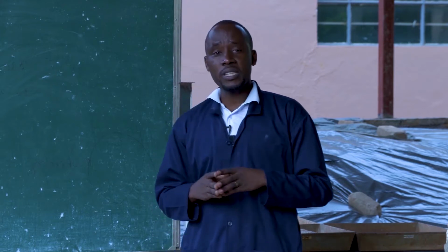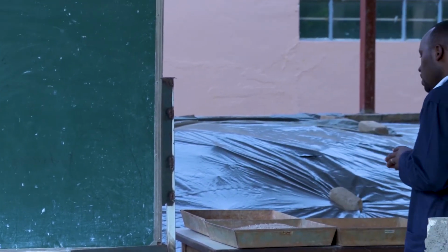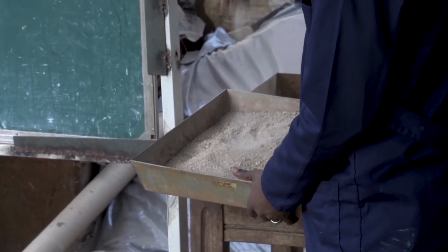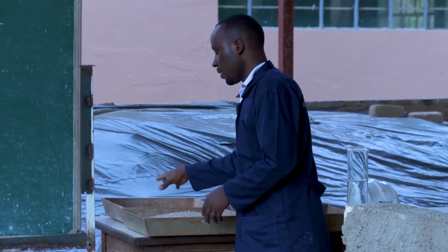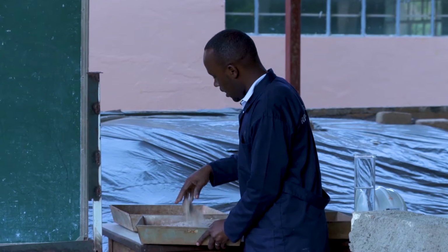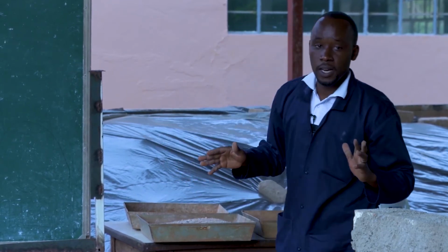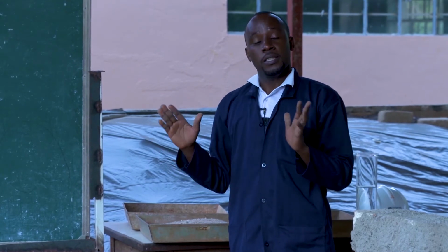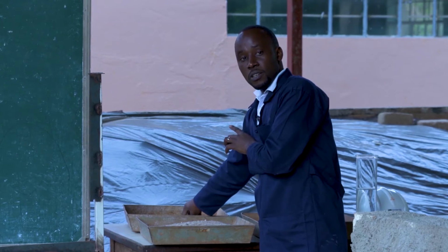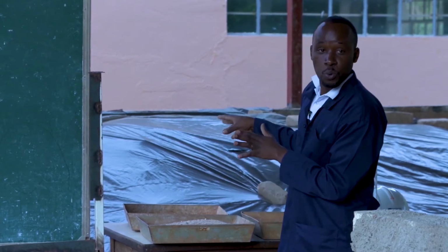Normally, in wall plastering, we need different types of material to perform that task. One of the materials used is sand. Here we have two kinds of sand. This is a coarse sand, and here we have a fine sand. Because our plaster has to be done in three coats, the first two coats must use this coarse sand. But finally, when we finish our wall with the finishing coat, we use this fine sand. That is why we have two kinds of sand.